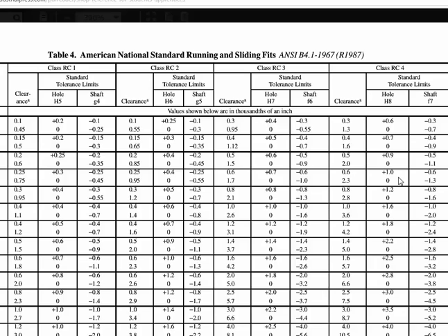We're looking right here where it tells us for the hole, in order to determine the tolerance range, we're going to start by adding nothing. So in other words, the max material condition size of the hole is going to be the nominal size of the part, 625 thou. Now the least material condition size of the hole is a little bigger, and so it's going to be increased by.